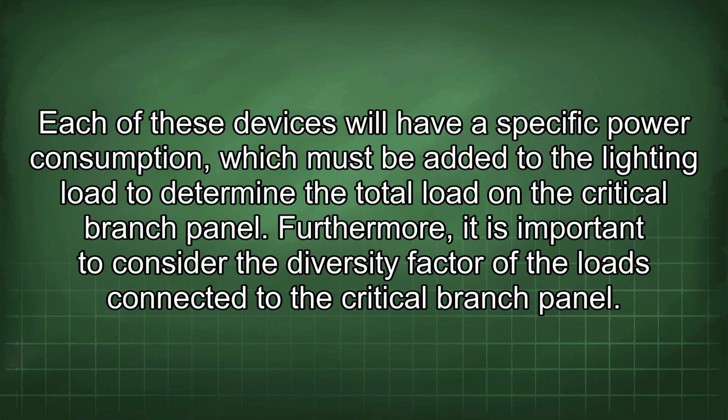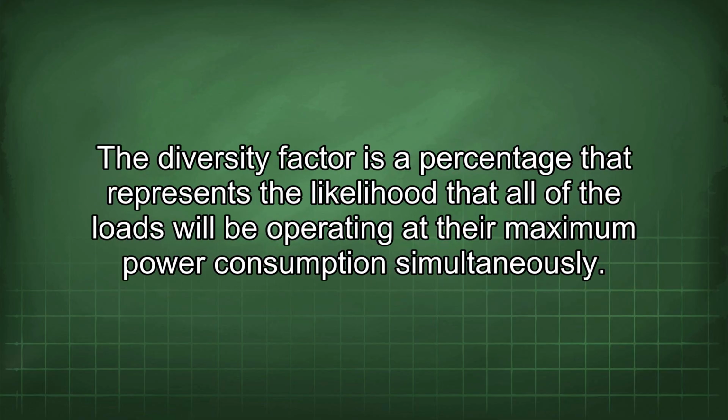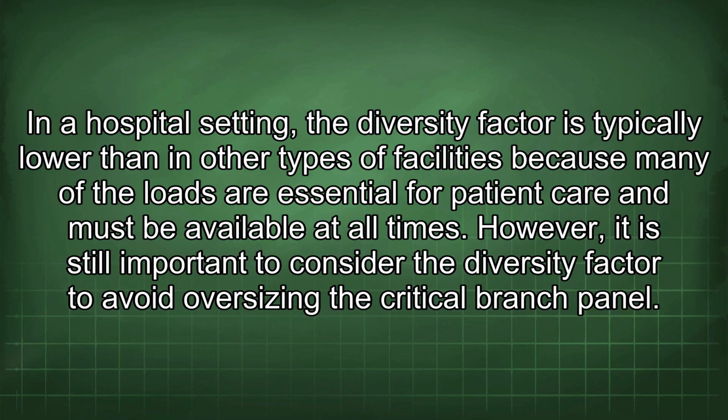Furthermore, it is important to consider the diversity factor of the loads connected to the critical branch panel. The diversity factor is a percentage that represents the likelihood that all of the loads will be operating at their maximum power consumption simultaneously. In a hospital setting, the diversity factor is typically lower than in other types of facilities because many of the loads are essential for patient care and must be available at all times. However, it is still important to consider the diversity factor to avoid oversizing the critical branch panel.